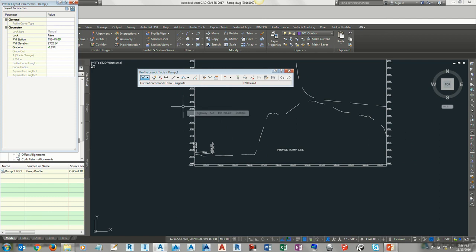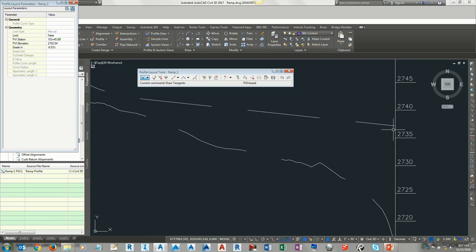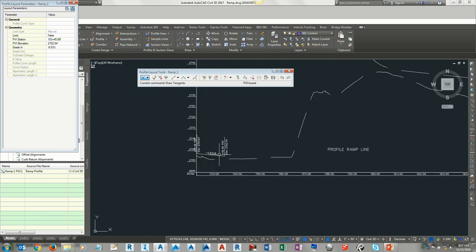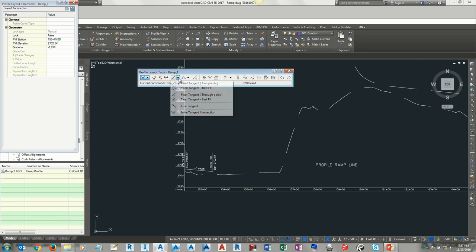Now, this grade that I'm looking at, you can figure out in multitude of different ways. That grade I know is 1.13. So I'll just use that. And I know I just calculated these things before. The elevation is very specific at this point. So it's going to go parallel, 0.24, a little bit lower than this, projected 2% down. So we know the end constraint. We know that it's going to go up from this at 8%. So I use this tool to solve tangent intersection.